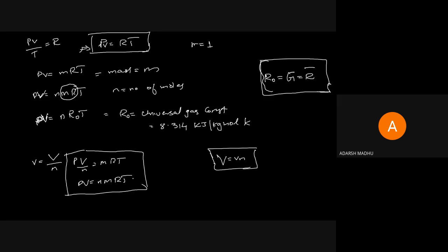Please note that for a question related to the normal perfect gas equation, we are using the PV equal to RT equation, and R is 0.287 kilojoules per kilogram Kelvin. If the question is asking for molecular weight, where capital M molecular weight is given for a perfect gas, like nitrogen or hydrogen, with molecular mass and moles, then we are using R equal to 8.314 kilojoules per kilogram molar Kelvin.